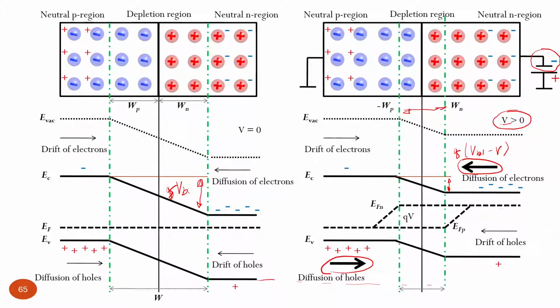At the same time, drift of electrons and holes doesn't change much. So electric field is reduced, so it's less favorable for charge transport with drift mechanism for minority charge carriers, but the current was so small there, like drift current, even with stronger electric field, that it just slightly decreases, but it doesn't make a big difference, so we can consider it constant.